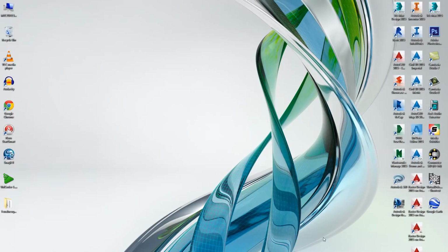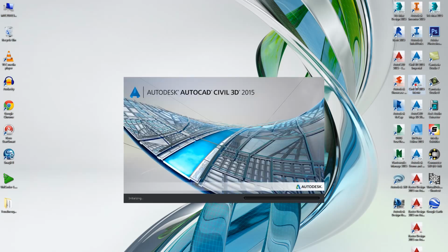If you don't have Civil 3D, you will still be able to use the project files once you get to 3ds Max Design. If you do have Civil 3D though, you will start from a blank page and create a surface based on the GIS data you just downloaded. Since we've established the project is in metric, start the metric version of Civil 3D 2015.